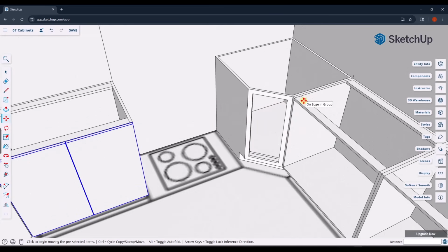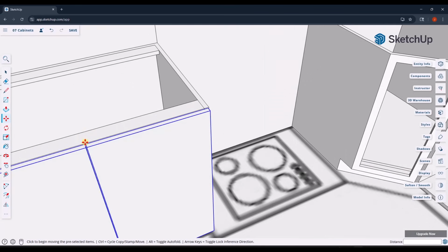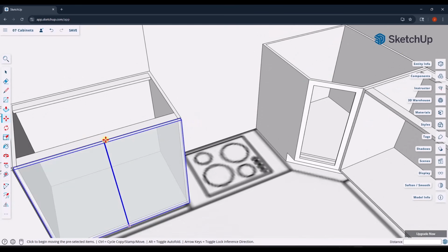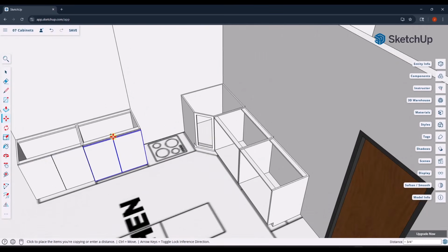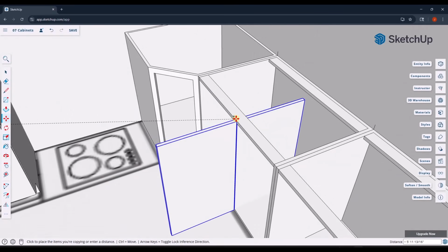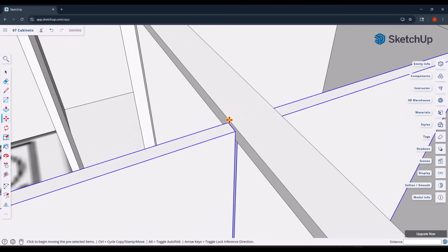And we want to do the same thing over here, but we want to rotate it. A lot of the time it might be easier because these are oriented differently. You might actually use the midpoint here as your base point. So we're going to use the move tool in copy mode. We're going to move over here, because then you can use the rotate tool.